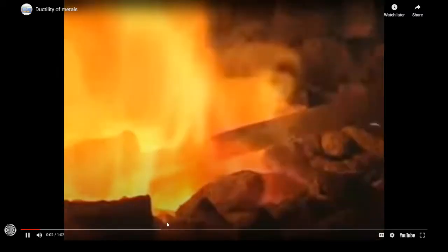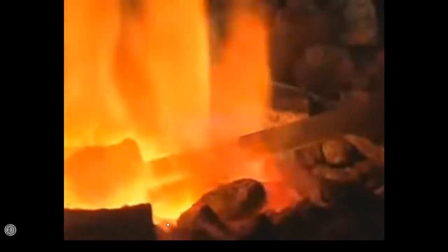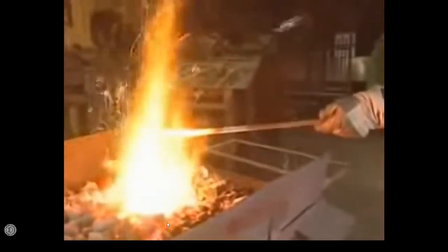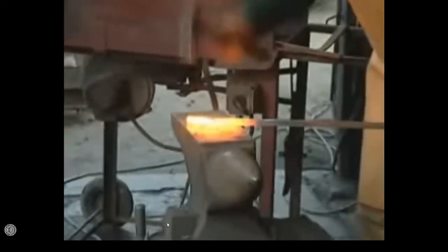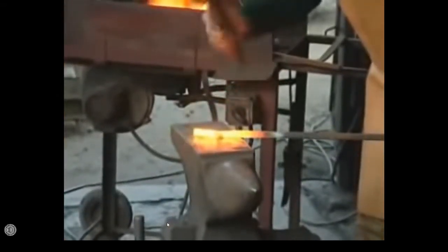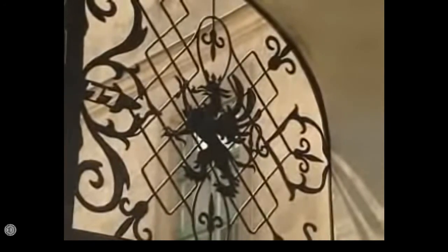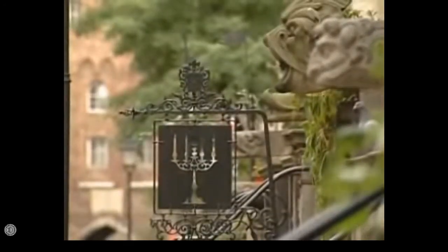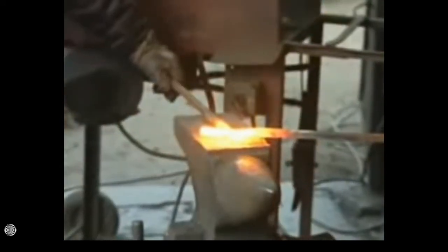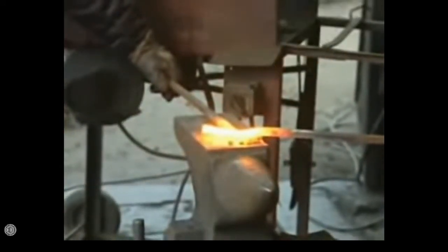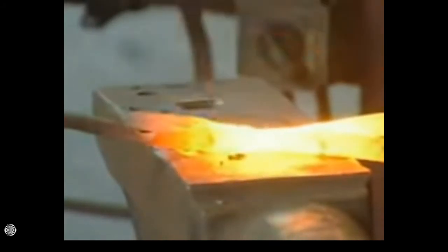So what characteristic would be able to determine the difference between those two? So this whole video is sort of a hint, so I'm guessing you could probably tell what that hint is right now. That hint is obviously the temperature, right? And so if you raise the temperature or you drop the temperature, it could change and it could determine whether that material is going to act in a brittle manner. That means it's going to break or fracture, or whether that material is going to act in a more ductile manner, which means that it's just going to bend.